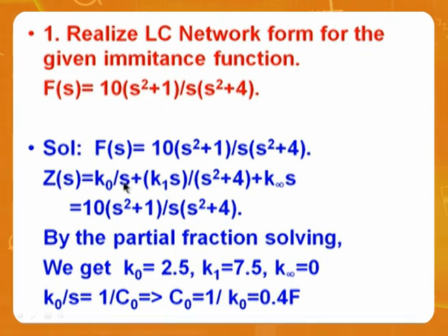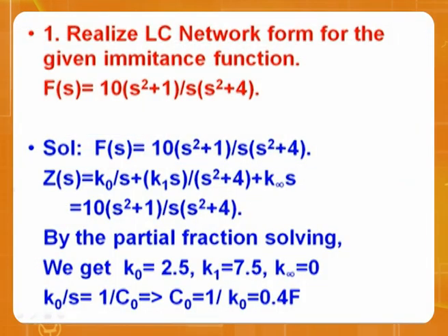What is K0 by S? K0 by S means, is it inductor or capacitor? It is capacitor, because in an impedance function, 1 by S means capacitor. Therefore, K0 is a capacitor, K1 has both a capacitor and an inductor, and K infinity is an inductor.